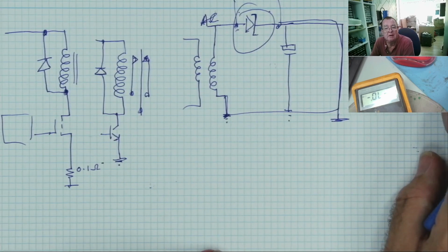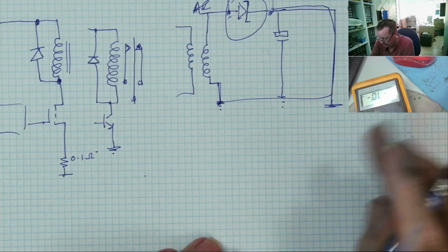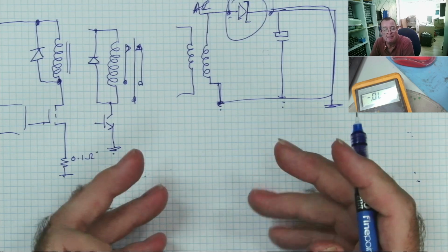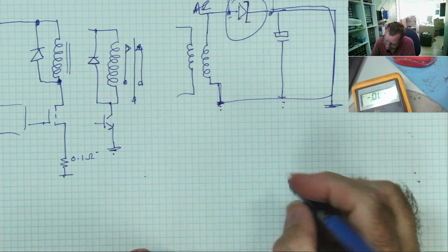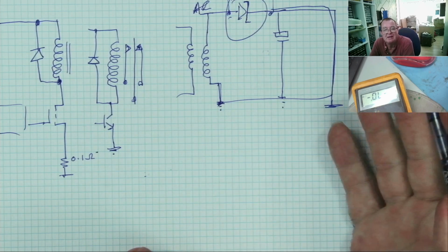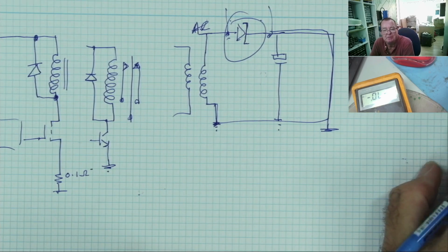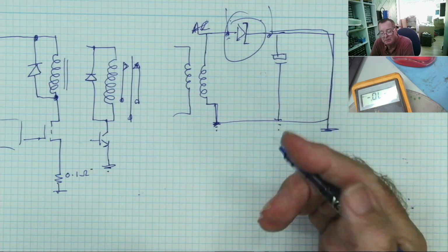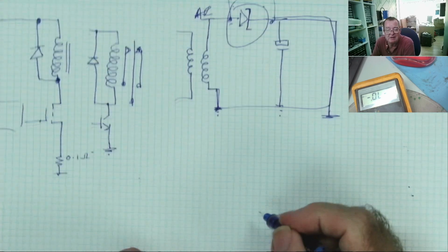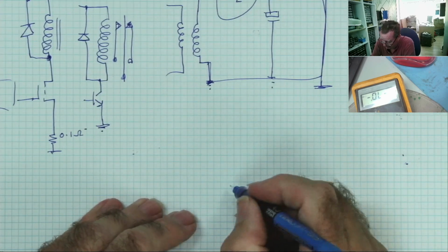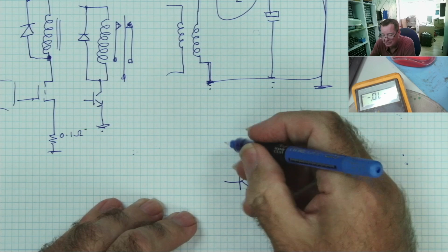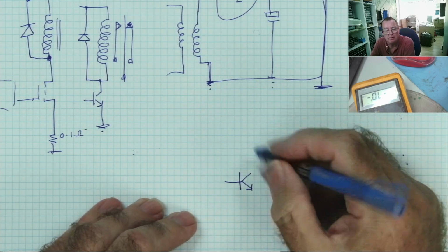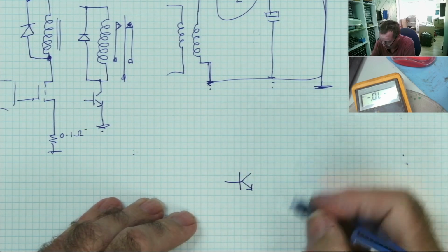Another good one which will fool you is power transistors. I can actually show you this. I have a good example of this. And you'll normally come across this in amplifier circuits in particular, but it could be any power transistor. So on a large power audio amplifier, your output stage will consist of a number of large transistors in parallel.